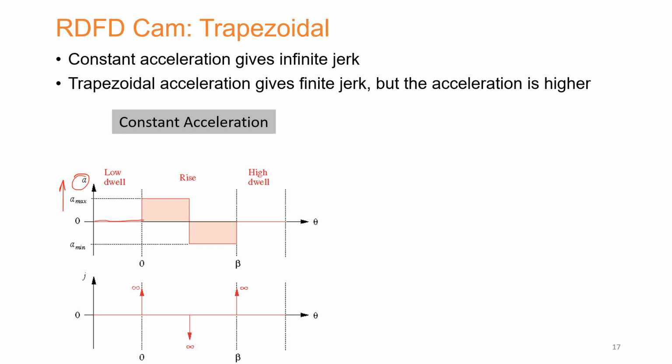segment, and once the rise is there, the acceleration is going to quickly jump to the higher value. Now this step function is going to be problematic when you take the derivative to compute the jerk, and you can see that an infinite spike in the jerk profile is visible because of the sharp rise in the acceleration. And then on the other side, when it tries to fall down quickly, you are going to find another spike corresponding to that. And once again it rises up, with this rising edge, you're going to have another spike appearing on the